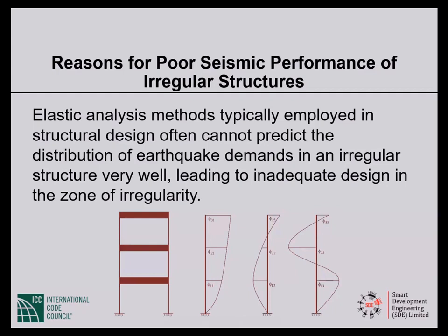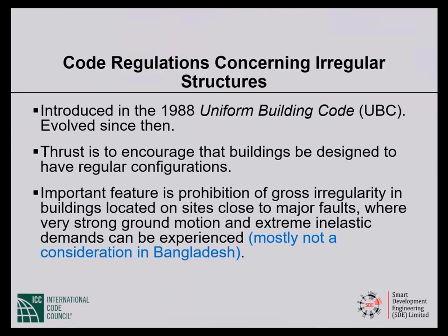So elastic analysis methods typically employed in structural design often cannot predict the distribution of earthquake demands in an irregular structure very well, leading to inadequate design in the zone of irregularity.